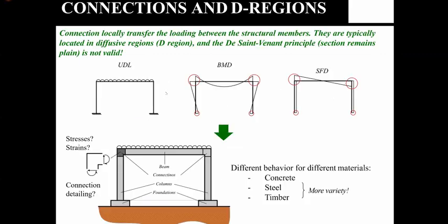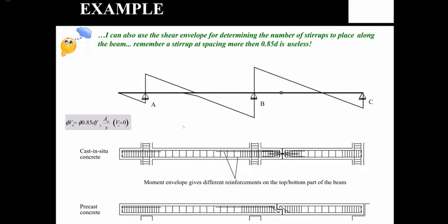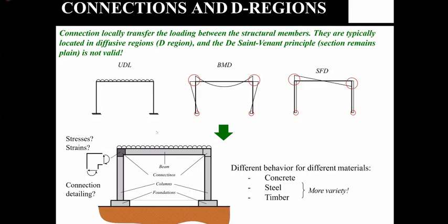So what I talked about so far is the member design, right? Now it comes to the connection, right? It is the one which transfers the forces between the members, say from the beam to column to foundation. As long as you have an intended connection, it transfers intended demands. So if you mess up your connection, then there is a possibility of unintended force transfers.